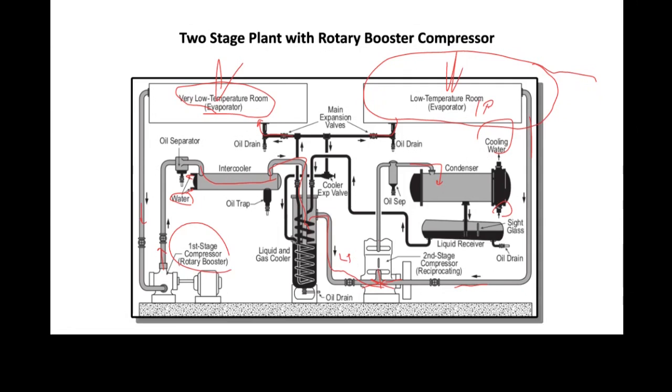All right, now let's take a look at, so we saw the intercooling, so we took a look at that volumetric efficiency end of things. We looked at the adiabatic versus isothermal end of things, and the volumetric efficiency increased by reducing the delta P across each compressor. Great. Now let's look at the net refrigerating effect end of things.